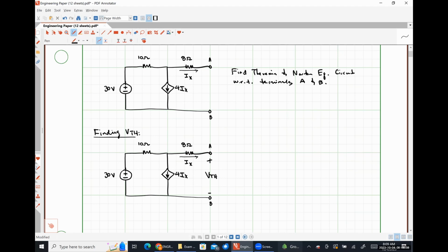So I'm going to assume that you said that just to annoy me, which is fair. Here's why I wouldn't use mesh analysis. There's only one mesh. Right? The right-hand thing is open circuited, which means it's not a mesh because there's no current flowing through it. So you can't even really do mesh analysis even if you wanted to. Good try though. So could we do voltage division to figure out what IX is?